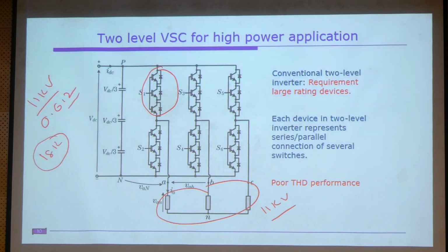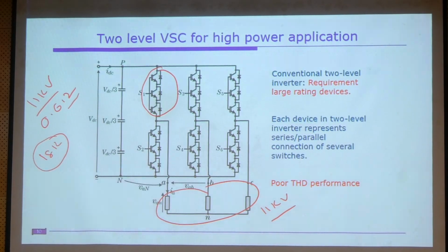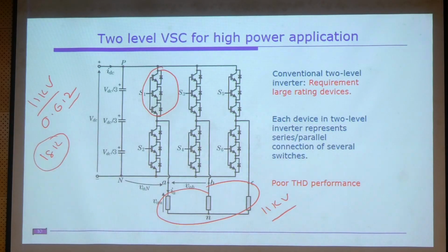One is the bond wire and the other is press pack. In case of bond wire, if it is exceeding the temperature limit or something, the bonds, the metallic bonds that will be there, will be opened, right? So that leads to the open circuit.